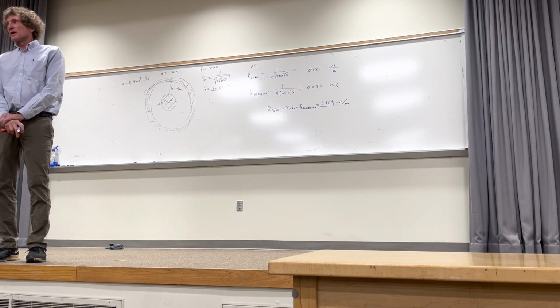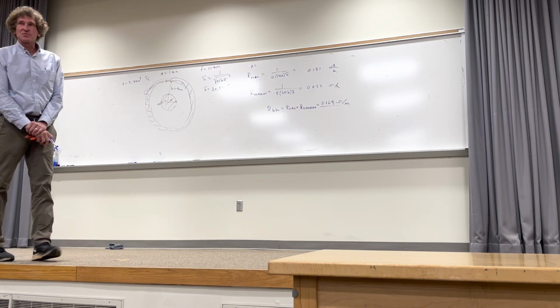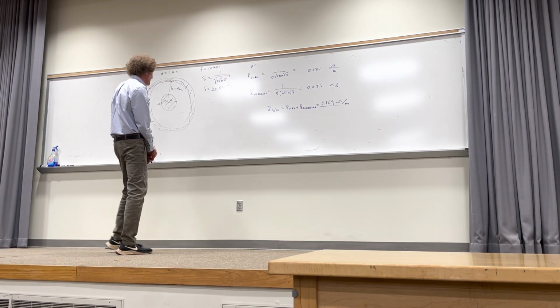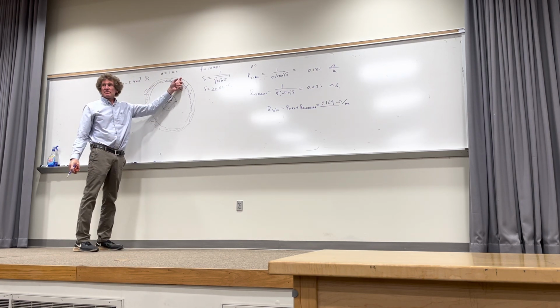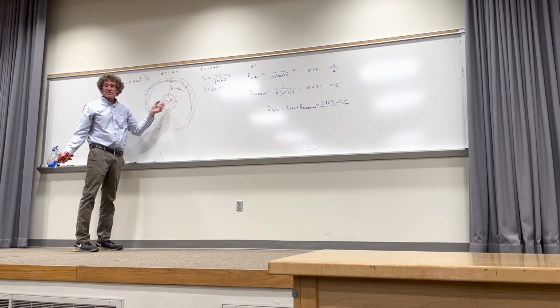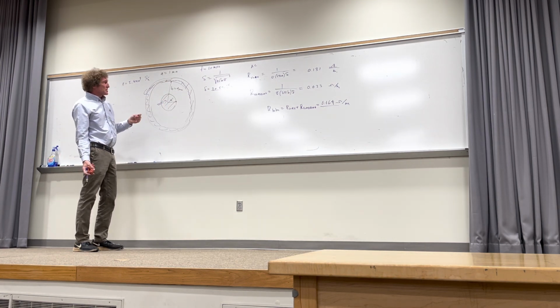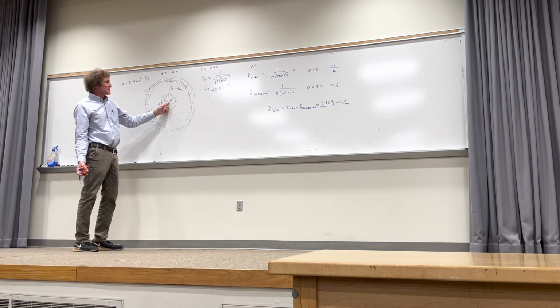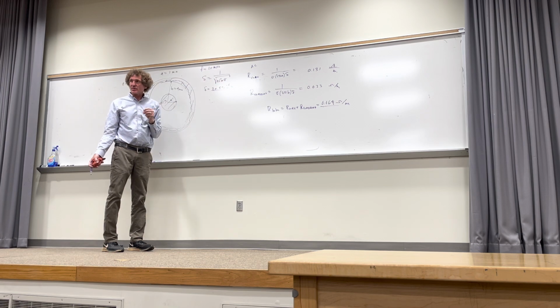Really, those problems, once you do a few, all of them fall suit. There's nothing tricky about it. The only thing, here's the trick. Not trick, really, you just have to be attentive. This could be made of copper, this could be made of steel. Follow me? It could be different materials. Has to be the same frequency. Mu could change too. If it was 1045 steel and the mu changed, then you'd have to change mu in there too. All right? If mu relative was 1,000, say. Okay? That's it.